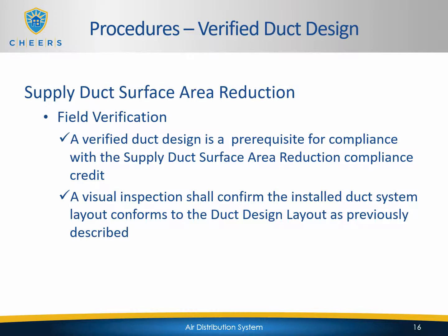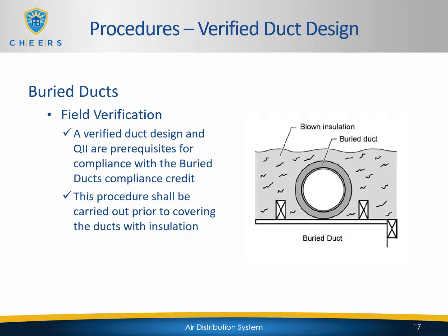For buried ducts, the field verification obviously still involves a verified duct design and QII. Those are both prerequisites for this particular credit for compliance with the buried ducts compliance credit. This procedure shall be carried out prior to covering the ducts with insulation. So if you have buried ducts as a compliance credit, a verified duct design and QII will also have to be performed in order to be compliant.